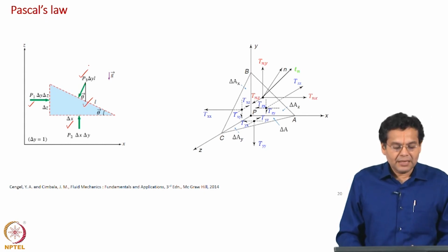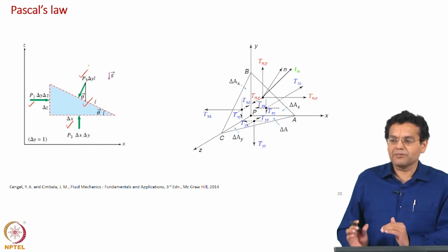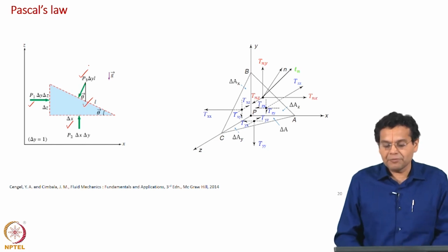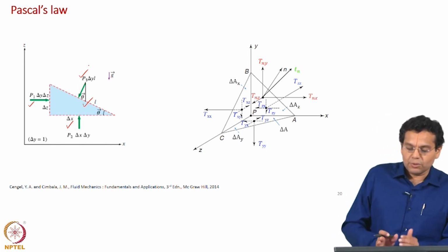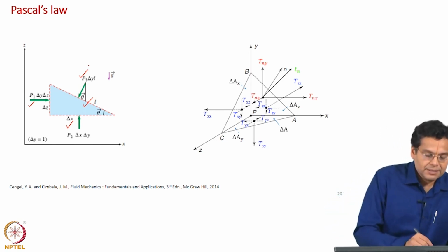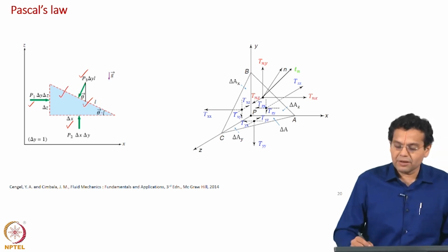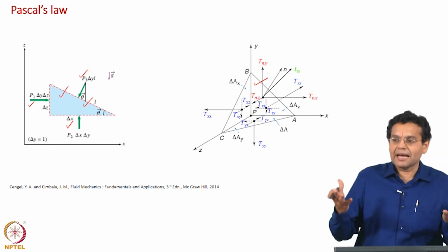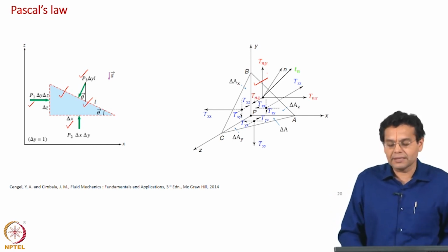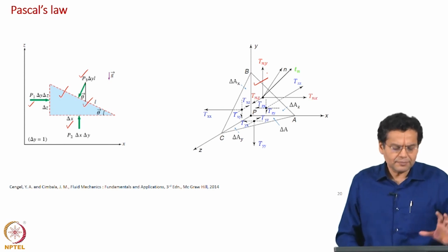This wedge shaped element is nothing but our 2D version of our tetrahedron, because we discussed under 3D condition, we took a tetrahedron. Look at one projection of that and then another plane attached to that. This is a plane at an angle theta with the horizontal. We also said we have a plane at any angle. So, both are equivalent, that is done for 2 dimensional case, we have done a 3 dimensional case. Okay, what are the other differences?